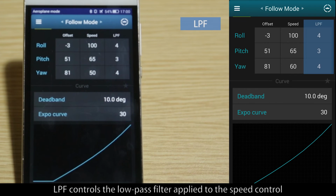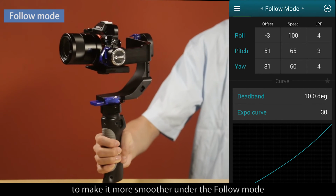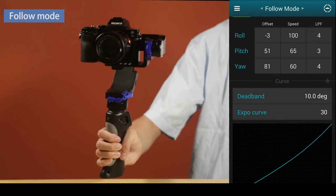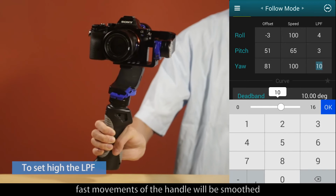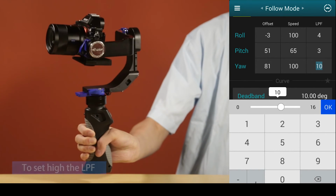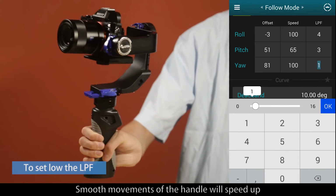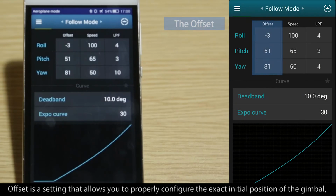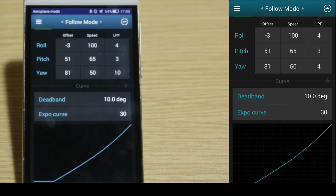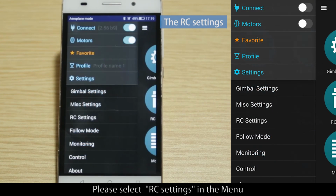LPF controls the low-pass filter applied to the speed control to make it smoother under the follow mode. If this value is set high, fast movements of the handle will be smoothed. If this value is set low, smooth movements of the handle will speed up. Offset is a setting that allows you to properly configure the exact initial position of the gimbal, and there is no need to adjust. The last subject is the RC settings.